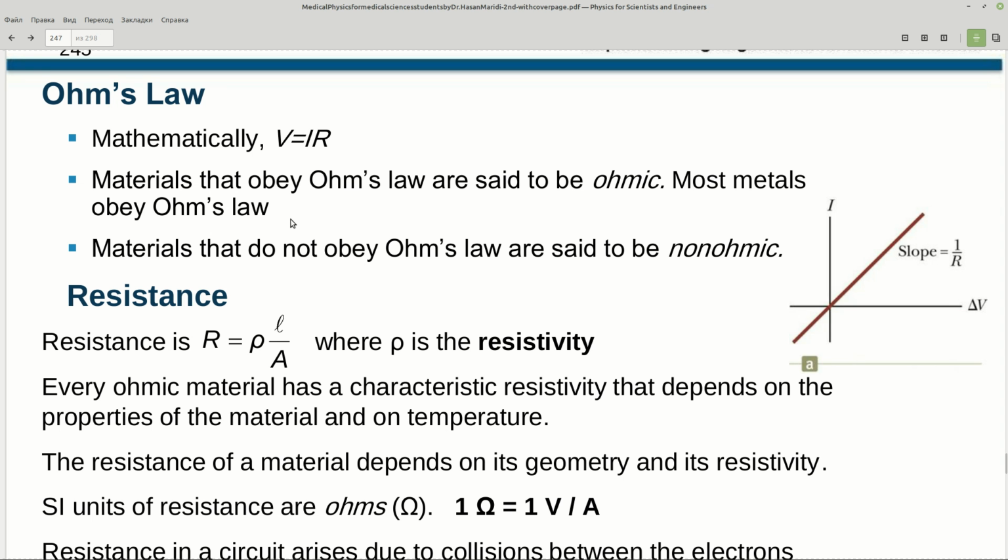When we put in the numerical values, r squared is your 5 micrometer squared, and the length will be 1 meter. But do not forget to convert these special units, millimeter and micrometer, to the international system unit, the meter.